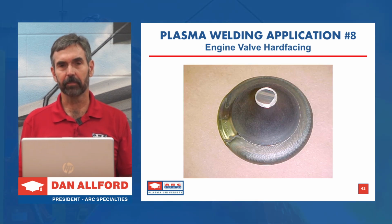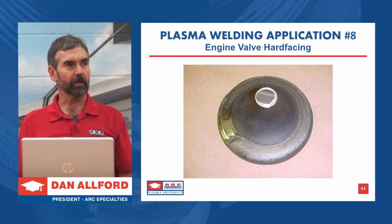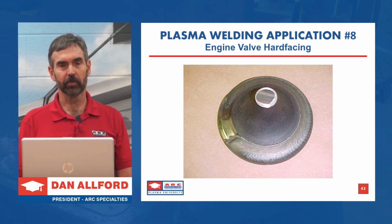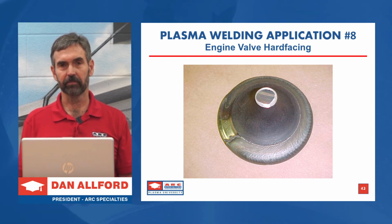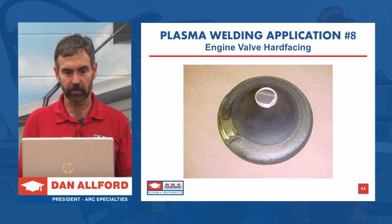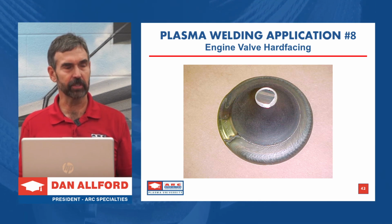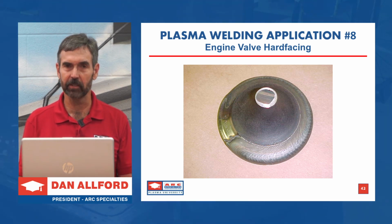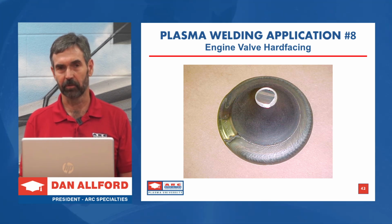One of the most common applications for plasma is in poppet valves for engines. Particularly after they phased out lead out of the fuel, we tended to have valve wear problems. And one way to overcome this is to coat the valve. So what you see here is a valve with the stems cut off, and it's partially welded, just to show you what we've done here. But that rim that actually seals against the seat inside the engine is coated with a high cobalt alloy to improve engine life.